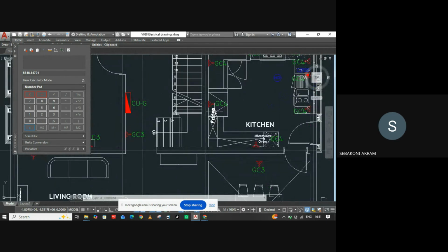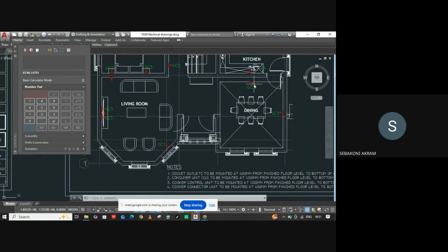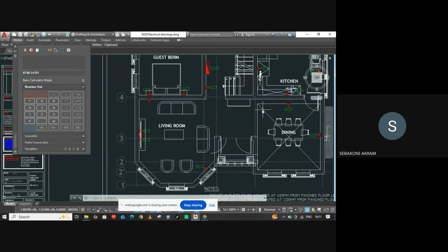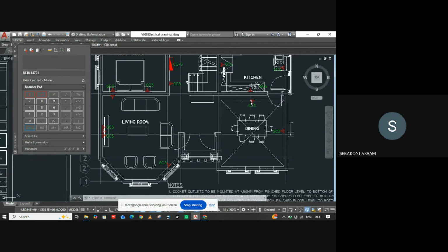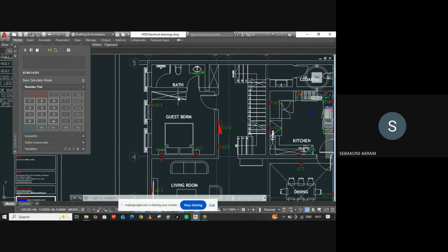Also comparing each socket, what do you expect here really? It's something small. So you can assume maybe here there is a charger, or maybe there is a woofer, there is a charger, they are charging from here. You estimate all those, because this is an estimated load. You estimate every appliance you would expect at the point where you've put your socket, you sum that up, you get that load. Are we together?